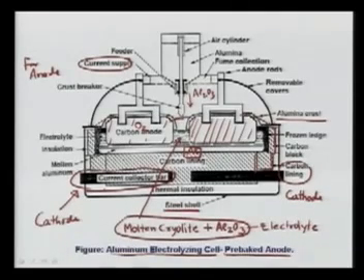Whenever you want to supply Al2O3, you bring what is called the crust breaker, you break the crust and put the alumina down there. The whole thing is filled with Al2O3.